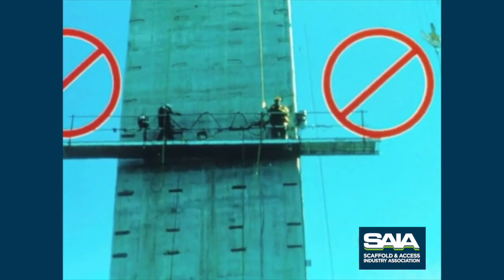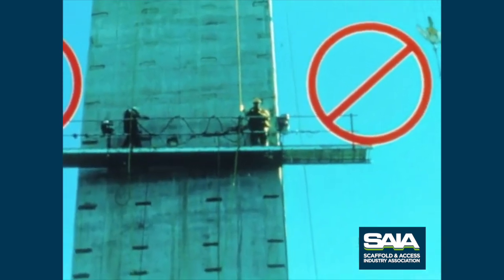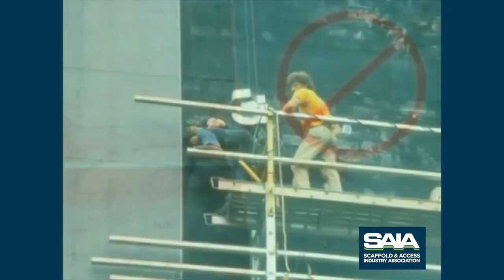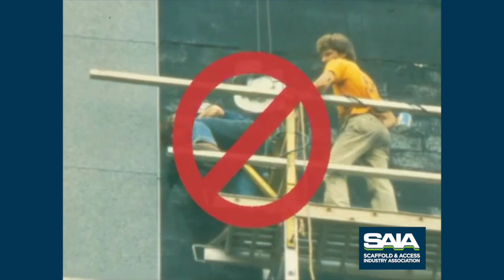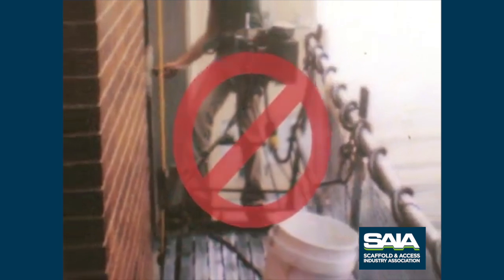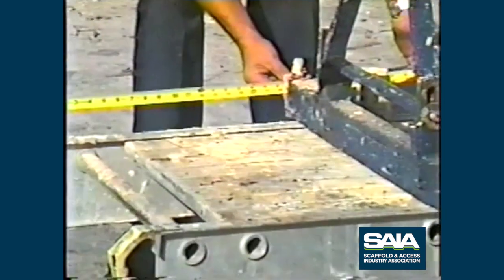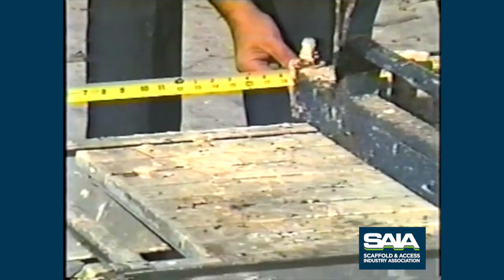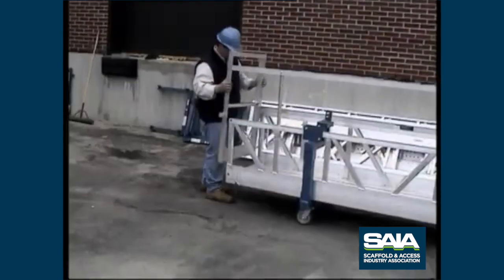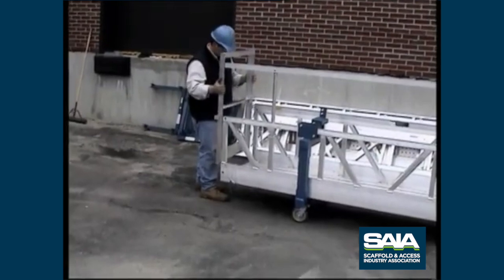Select the platform that is of the proper length. The platform shown in this scene is much too long. However, if the stage is too short, workers will be tempted to stand on the stirrups or end rails to reach out further to complete their work. This is an unsafe act. Do not do it. Stirrups should be installed 6 to 18 inches from the end of the stage for fixed-length platforms. When so installed, non-walk-through stirrups serve as end rails.